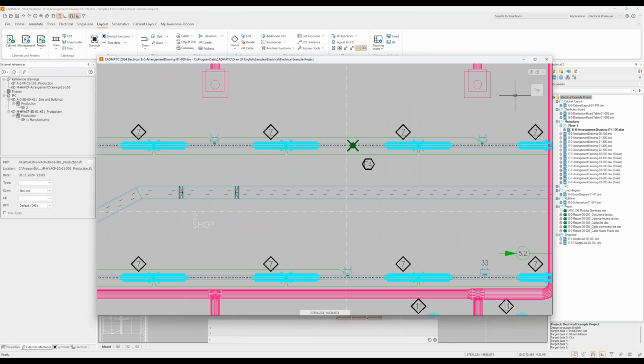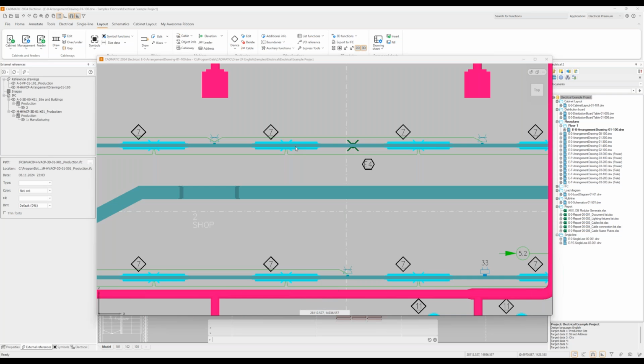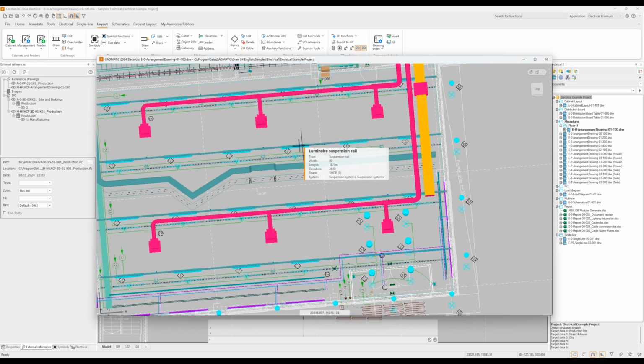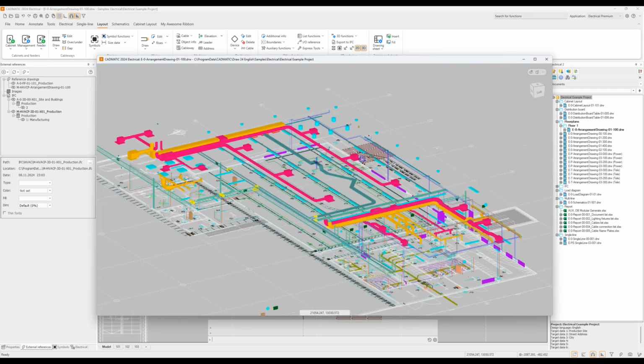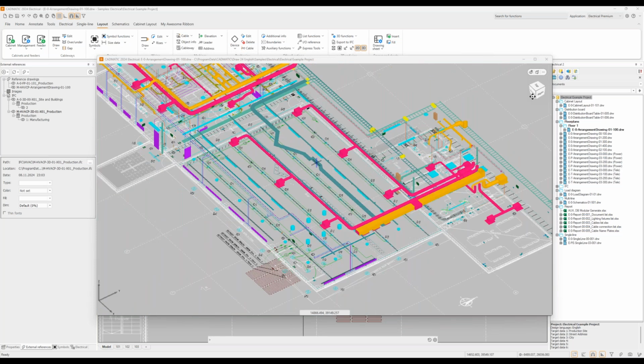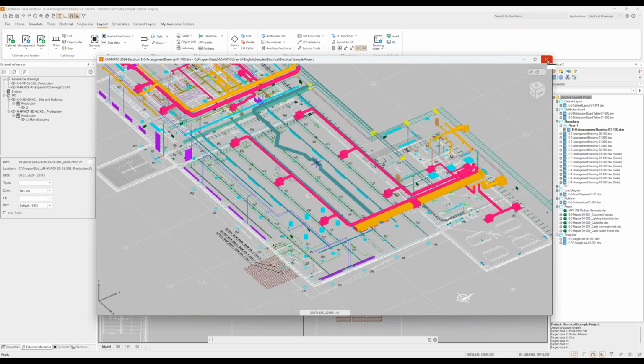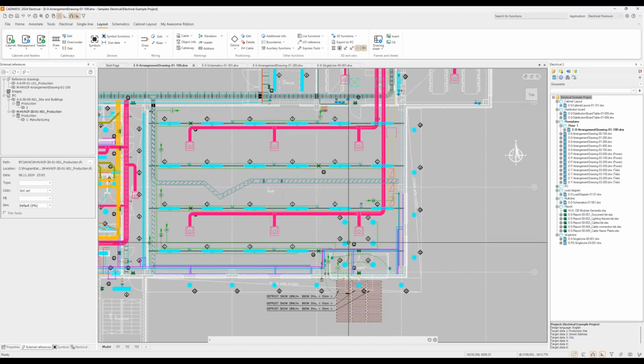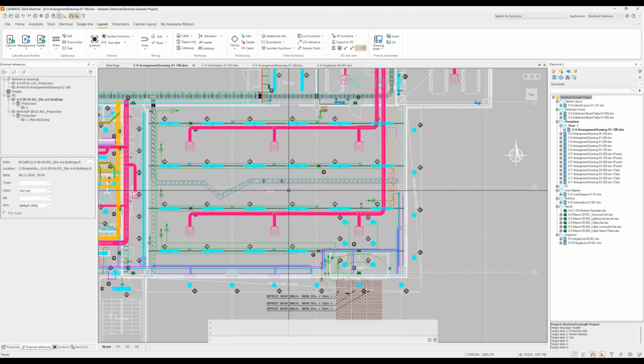You can rotate things. You can just press Control and click mouse there. You can rotate this one, use the View Cube to rotate however you like. Now there is a whole other webinar about this View Cube, and also some training materials. You can go into this a bit deeper. But from this point on, I will only use this one view, so maybe for you guys it's much easier to follow.